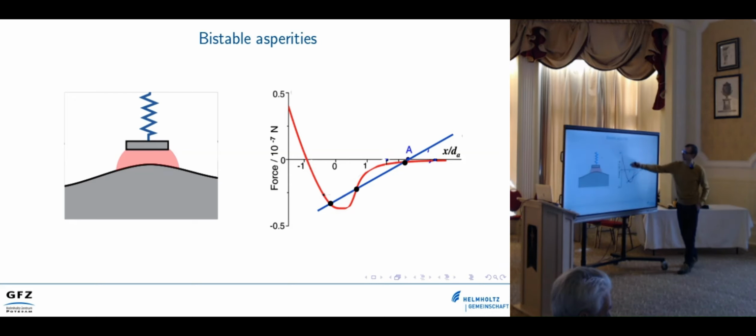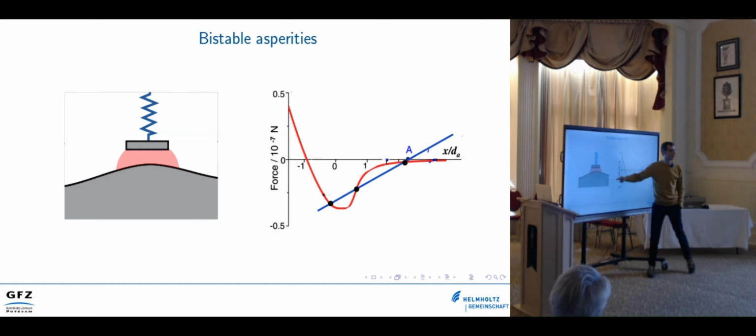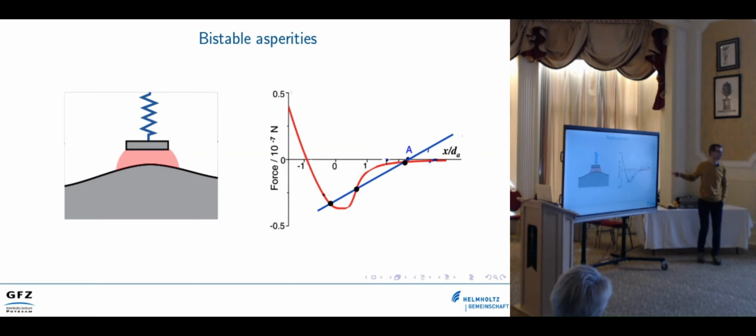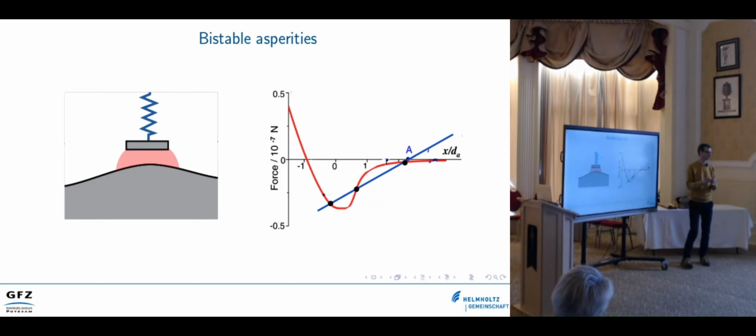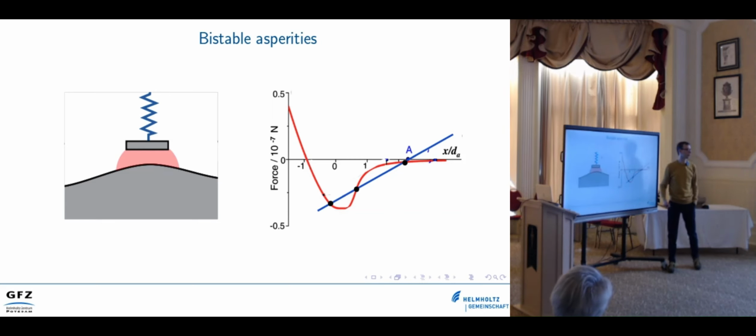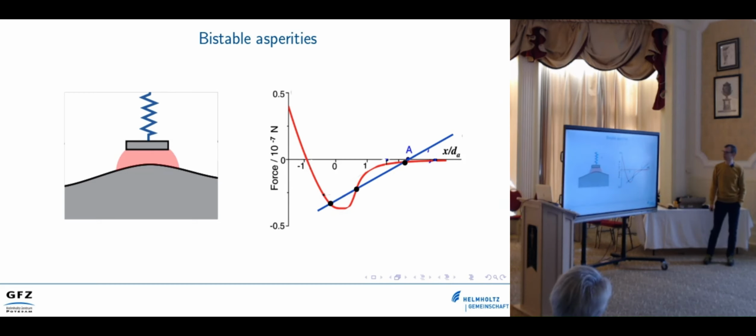And this is, for example, a Lennard-Jones potential between these two contacts, which means that if the contacts are far away, we don't have any force, so they don't notice each other. But when we move closer with these two surfaces, we actually generate some attraction, which can be, for example, a van der Waals force between the two different sides of the material. So we have a force that pulls these sides together, but when we push them too close to each other, then of course they get in contact and you have repulsion. So you have a force that pushes these two particles away.